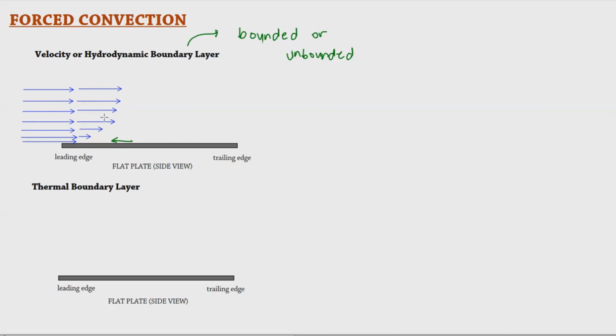So this is how it goes for our fluid. So imagine the resistance that is offered by this flat plate, and this resistance would be able to retard this streamline that is near the edge. So we call this condition the no slip condition. Let me just write it right here. So this condition, the no slip condition, means that the velocity of the streamline near the boundary would be equal to 0. So in this case, that's how it goes for the flat plate.